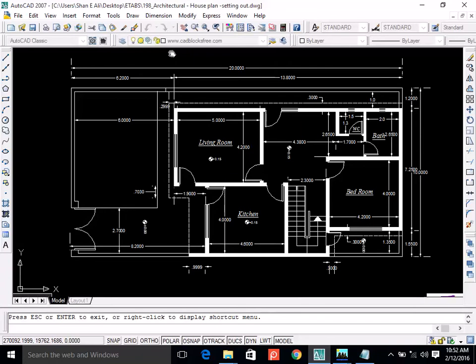So it is difficult to draw the grid lines according to the true shape of the building. It is laborious, and also you will make some approximations. So the better way is that you draw the grids in AutoCAD according to whatever the shape is, and then import those grids in ETABS.